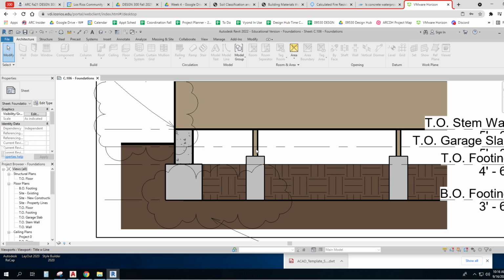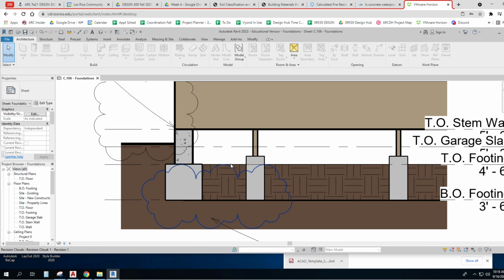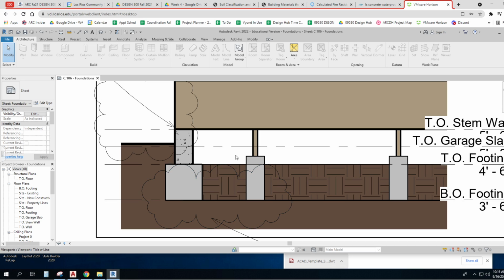We don't tend to just sink 4x4 or 6x6 posts into the ground and set them. We tend not to do that in California so much because we have some pretty strong environmental rules, and people are concerned, of course, that the wood will rot out where it hits the ground, where the water and the pests can go, particularly if it gets wet then dry, then wet then dry, and bugs attack and bugs go away and bugs attack.